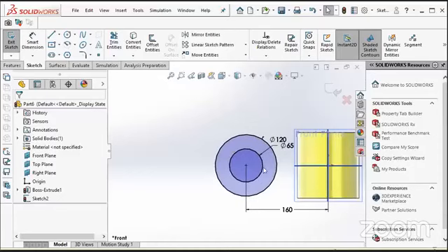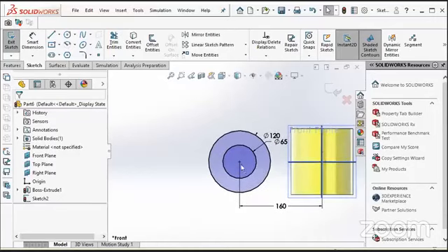So my sketch is fully defined. The fully defined sketch means that it has defined all the dimensions, which cannot be disturbed when you are doing modifications in the part later. Otherwise, if your sketches are not defined, after the modification your reference sketch will be disturbed and your whole assembly or part protrusion will be disturbed as well.